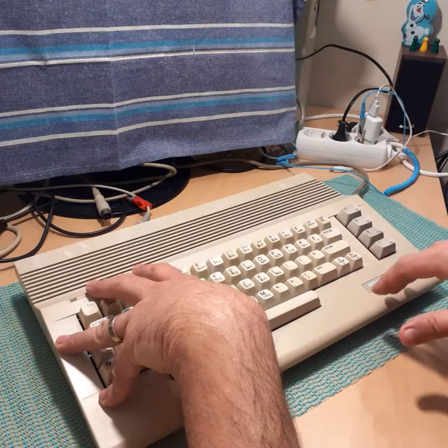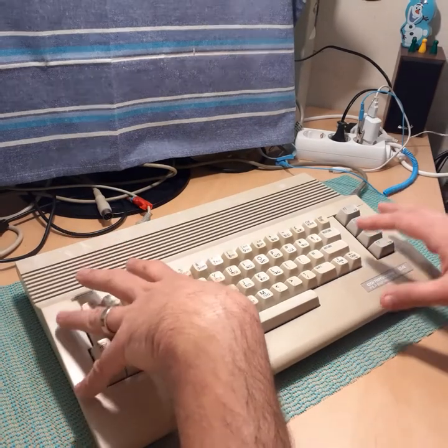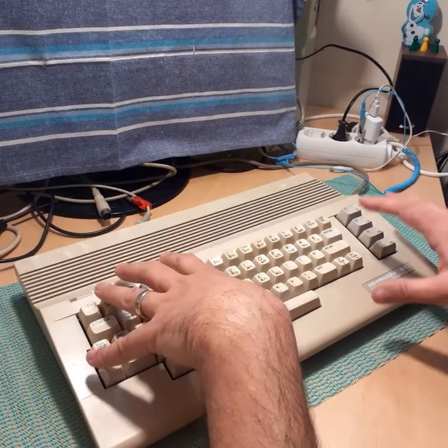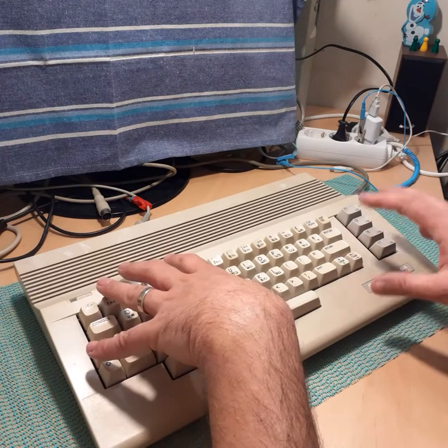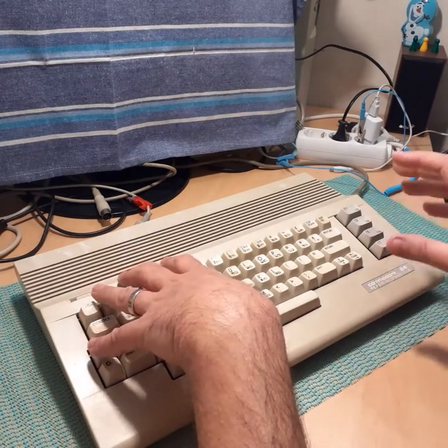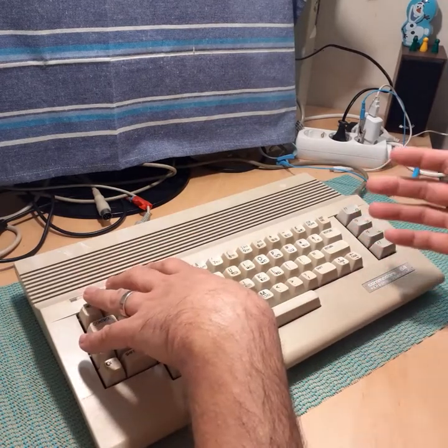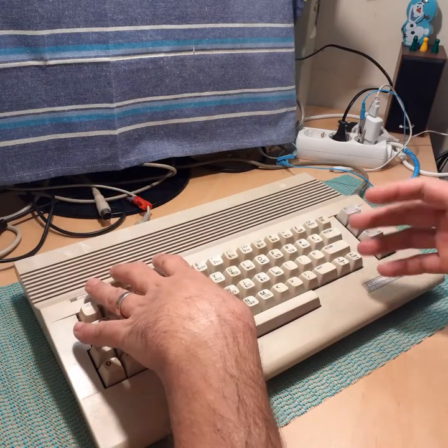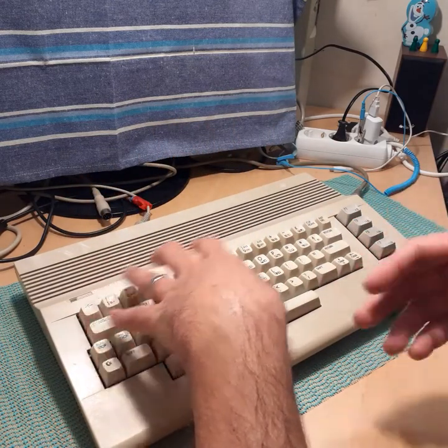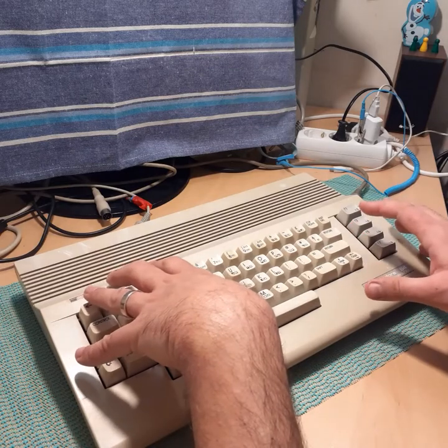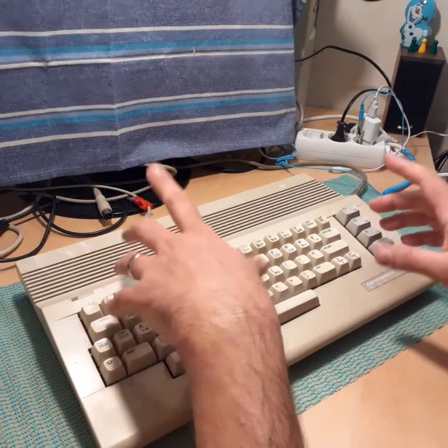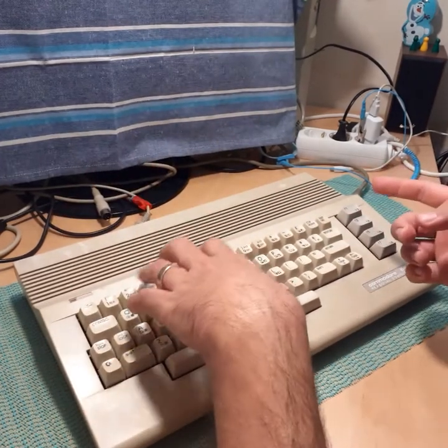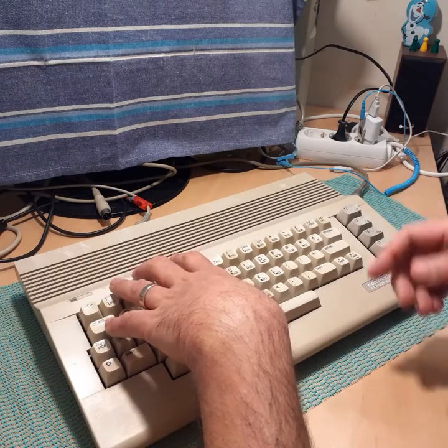Now, for proper RS232, we need negative voltage to represent the logic high and positive voltage to represent the logic low. And this is a very robust method for data transfer. But on Commodore we have 0 volts for logic low and 5 volts for logic high. So what kind of protocol is that? Well, this is what we call TTL serial communication. And believe it or not, this is so much better today than it ever was back then when Commodore 64 was on the market. So, let's check it out.